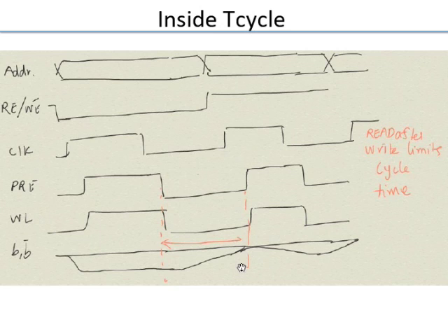So this value, say, had bit 0 and bit bar 1. As it's pre-charging, it had better pre-charge and equalize the two bit lines, because any residual voltage difference will eat into your voltage margin, because the memory cell has to overcome that and turn the bit, and get me the voltage of the opposite polarity.